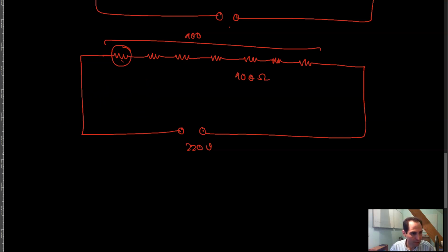Now what happens here is that some people know this, and when one of these lamps is damaged, then they short out these two poles over here. They short this out because the lamp is not connected anymore. The lamp is basically open now. It is an open circuit now. So then they connect the whole string at these 2 points. They short circuit these 2 points, and then that means that the current can still go through the circuit.